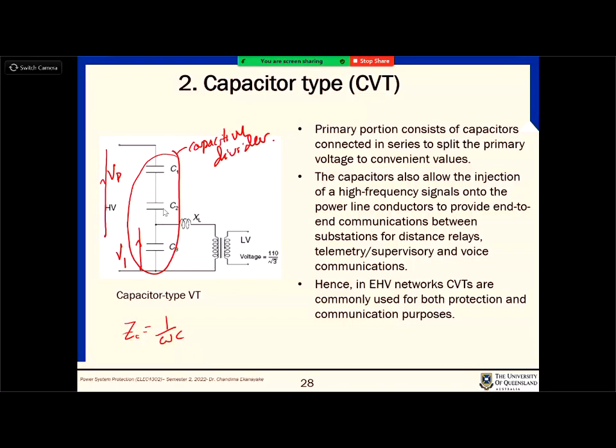So that is what is called power line communication, or PLC, so that you can send the communication signals through the power line other than the power. The information goes from here, through this VT, you feed the information to the line, it goes to the other end, then you have to get it back.